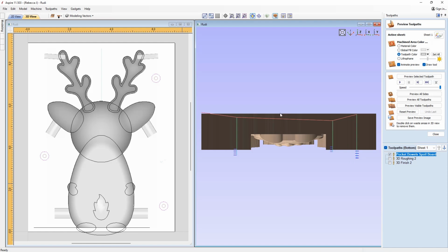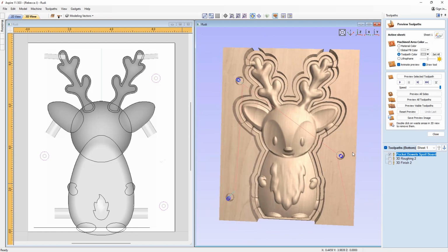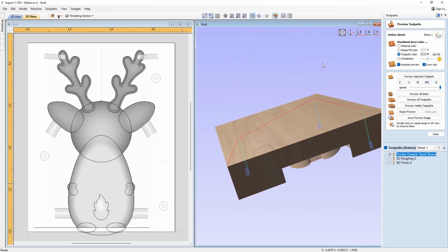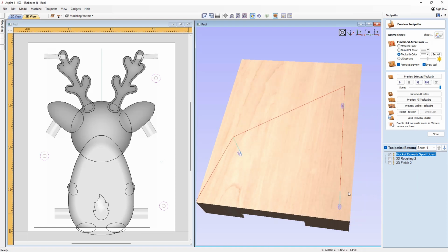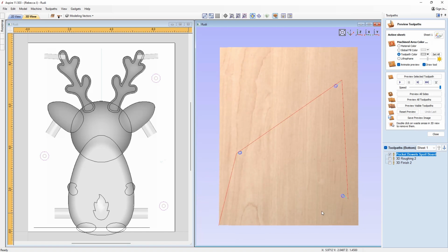Once we've got the dowel holes in position, we can take our block of material with our dowels in, simply turn it over, locate it to those dowel holes, and then secure it by screwing our material into the spoil board. Then we have perfect alignment, and we can now move on and think about the other toolpaths, whereby we're going to go into the 3D roughing toolpath.